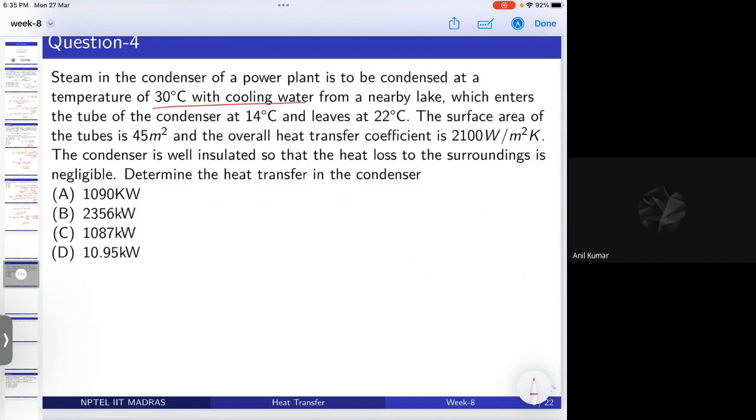It is a surface temperature actually. So constant surface temperature condition is made. No, no. It's the steam condensing. So whether the steam can condense at 30 degrees Celsius. Okay, because of the condensation of the steam, the tube wall is maintained at 30 degrees Celsius.